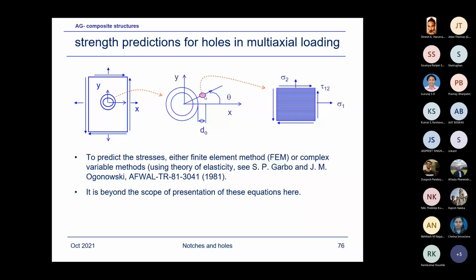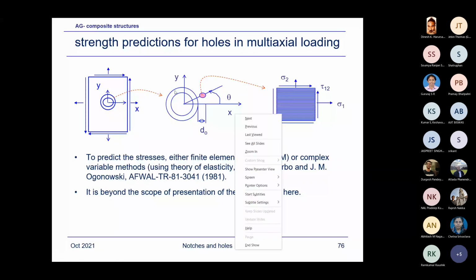Now, suppose you want to use the stress concentration approach, rather than using the stress at the characteristic dimension for a larger hole. When you are doing the finite element modeling, you may have beam elements along the whole boundary.